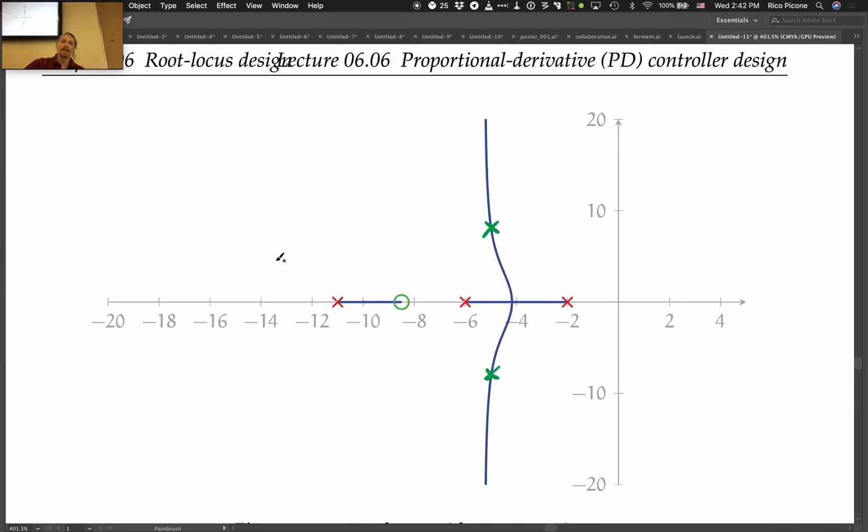So there is this pole pair, but remember, we don't get to decide where this other pole is. It could be here, it could be here, somewhere along this branch, right? But it's just going to be somewhere. And our factor of 5 rule of thumb for using the second order approximation is definitely violated here. So we don't know how accurate we're going to be, because the psi would depend on the second order approximation.